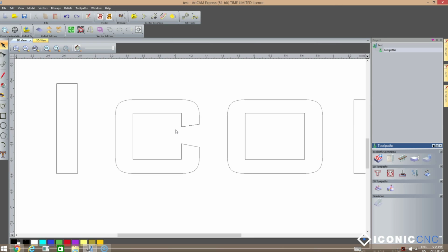The other option it gives me is to do a veneer inlay as well. So supposing I want to do exactly that same project, but only as a veneer, I would do a pocket in the black walnut of, say, 1/16 of an inch, then lay the veneer out on my machine, cut the piece out.